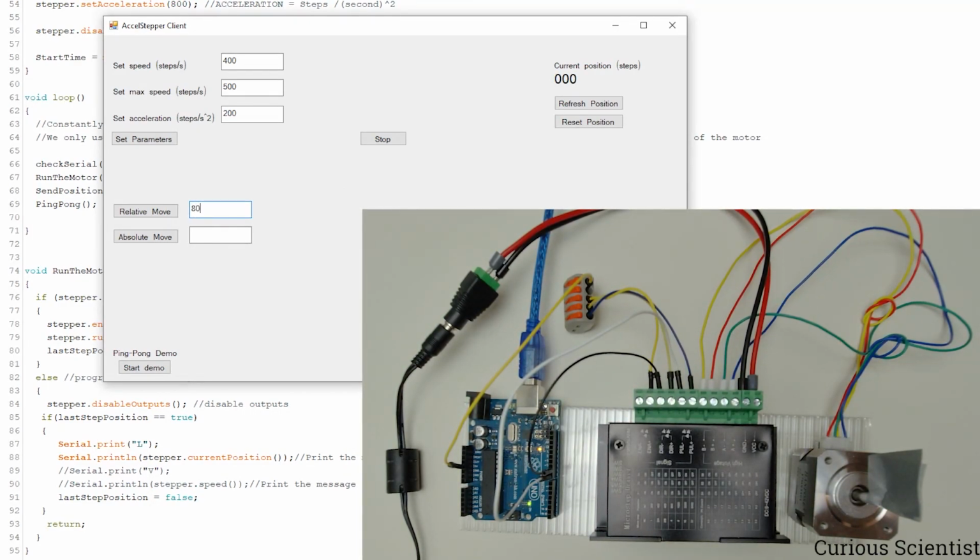let's say 8,000 steps. And why 8,000? My controller, the TB6600, is set with the dip switches, based on this table, to 800 microstepping. So one revolution will take 800 steps. So if I move 8,000, that will be 10 revolutions for this small flag. So now the flag is at the 12 o'clock position. So we should expect 10 revolutions if this works as it should.